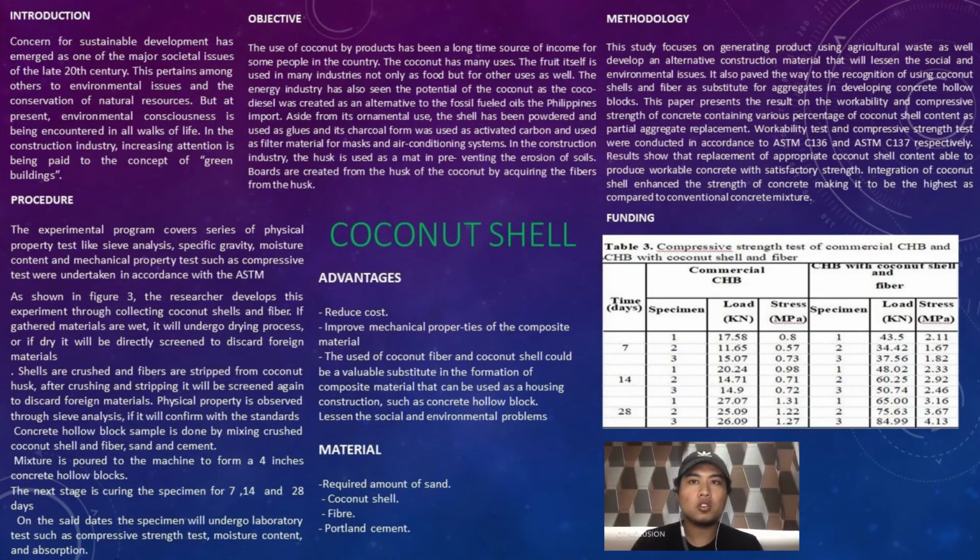As the conclusion, this study found that the inclusion of coconut shell as a partial aggregate substitution decreases the concrete workability owing to its shape and rougher surface. Be that as it may, it is interesting to note that the substitution of natural coarse aggregate by coconut shell resulted in an increase of compressive strength compared to the conventional concrete mixture.